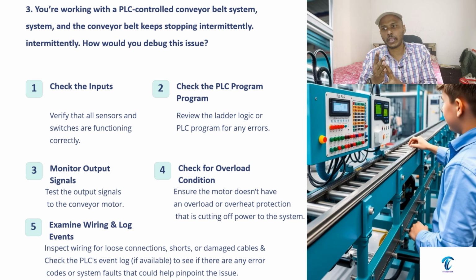And if the input is coming and the program is fine and it is generating output, but it is still not running, then you have to look at the output signals. You can even manually turn the outputs on and see.